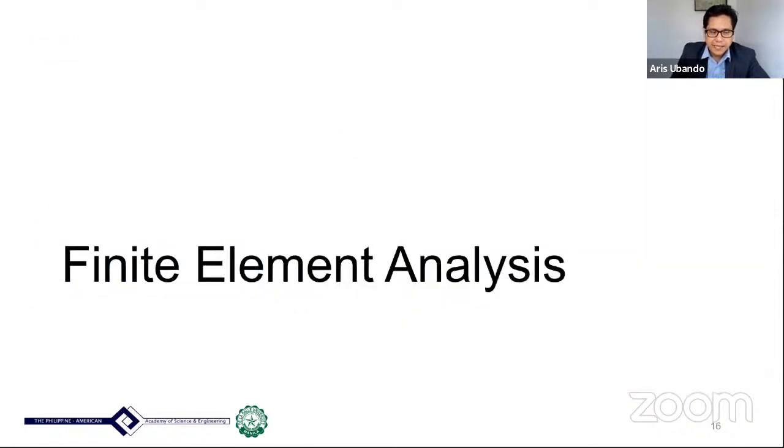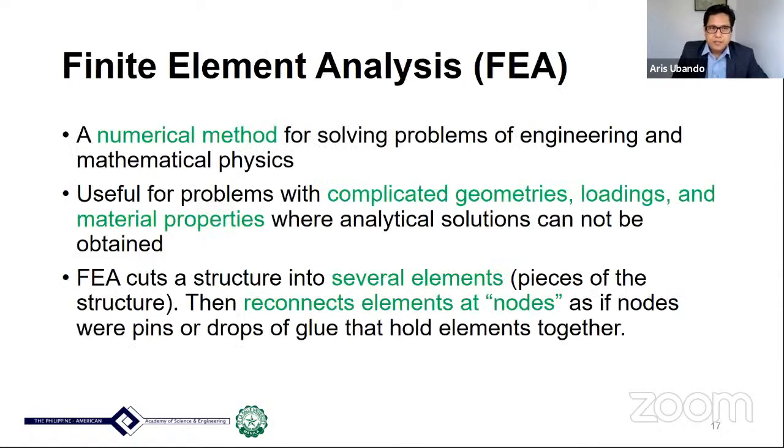So let's go now to the details of the finite element analysis. Finite element analysis, or FEA, is a numerical method for solving problems of engineering and mathematical physics, useful for problems with complicated geometries, loadings, and material properties where analytical solutions cannot be obtained. FEA cuts, or meshes, a structure into several elements. So we subdivide the structure into smaller pieces.